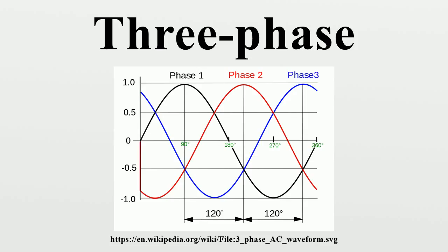Unbalanced systems. In practice, systems rarely have perfectly balanced loads, currents, voltages and impedances in all three phases. The analysis of unbalanced cases is greatly simplified by the use of the techniques of symmetrical components. An unbalanced system is analyzed as the superposition of three balanced systems, each with the positive, negative or zero sequence of balanced voltages.